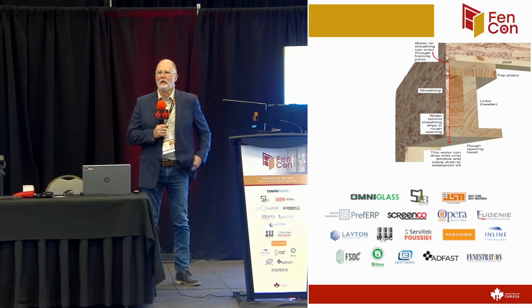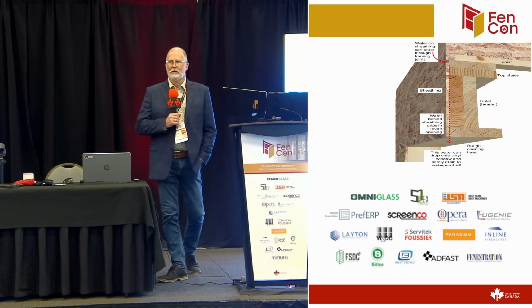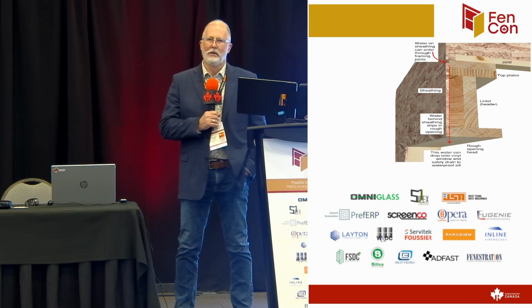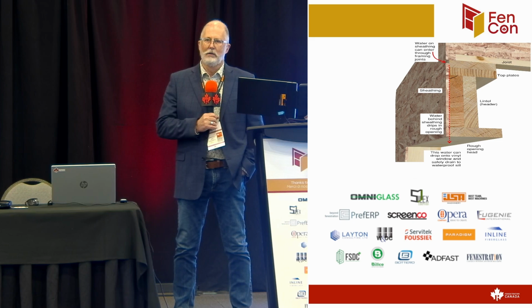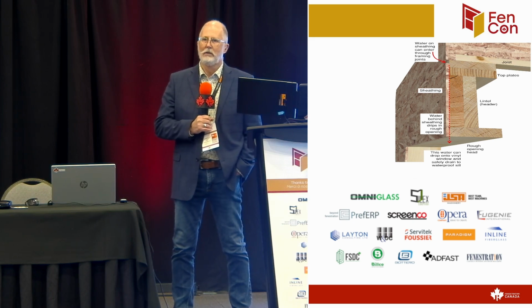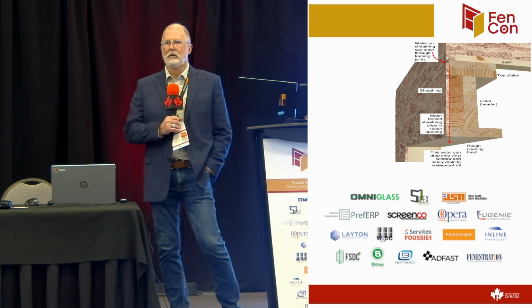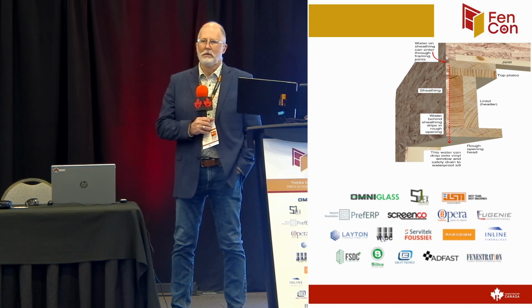To add to that, the last piece is the lifespan of those building materials, potentially with the air vapor barrier on the outside, say relative to the four-sided seal, where you're using a peel and stick. The lifespan of that material might be 40 years, 50 years, whatever it is. So you're thinking of the worst case, or the weakest link within that building assembly.